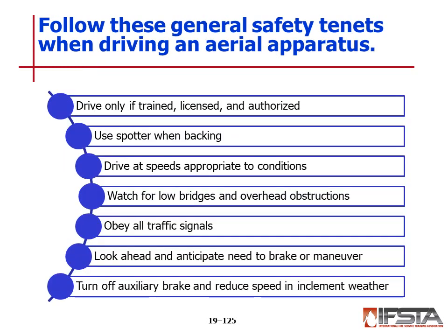Drive only if trained, licensed, and authorized. Use a spotter when backing. Drive at speeds appropriate to the conditions. Watch for low bridges and overhead obstructions. Obey all traffic signals. Look ahead and anticipate need for brake or maneuver. Turn off auxiliary brakes and reduce speed in inclement weather.